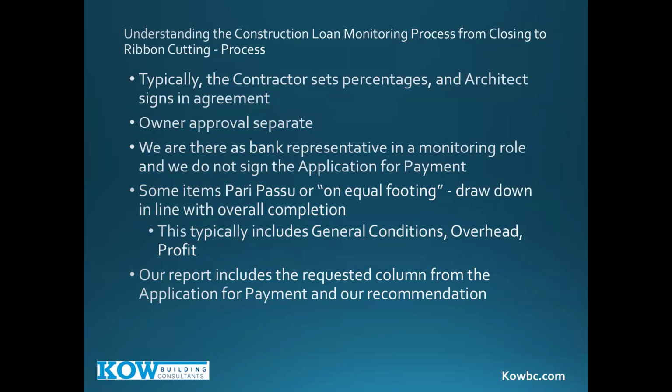Typically, the contractor will set the percentages, and the architect signs an agreement when we're all in agreement. That's called the pencil rec. It's not usually a pencil now. I remember the days. I got some snow on the roof of my head here. I've been doing this a while. When it was a pencil rec, it was literally pencils or pens out, marking it up in the field, and then they would correct it and send a clean copy.